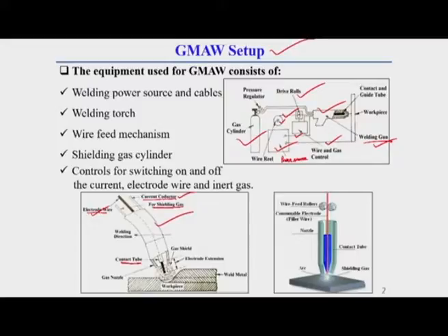So what happens once the welding starts? Here one thing you can easily observe: in the middle, an arc is generally developed by this welding gun. In front of this welding gun, generally some nozzle is used. Through this nozzle, the gas is emitted out to the weld pool. This is the gas shielding, which shields both the arc as well as the weld pool.